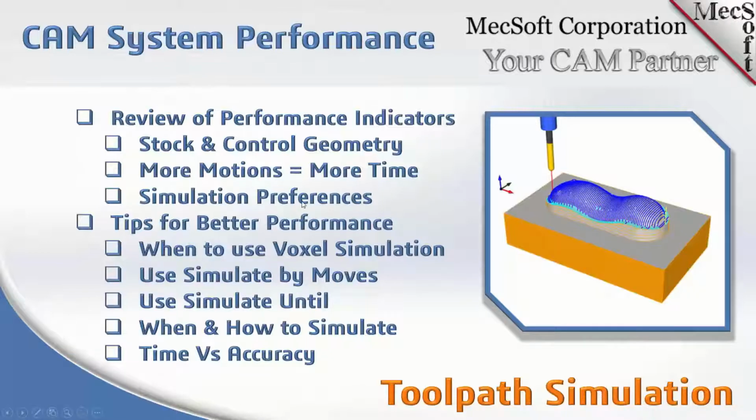Simulation preferences obviously also play a major role in how fast you can get through a simulation. Now, some tips related to increasing your simulation speed. We have different simulation models. One's called a voxel model, one's called a polygonal model. Just to mention, if you're using the Express configuration, you only have the voxel model, so you don't have the higher accuracy polygonal model simulation. I just wanted to mention that.